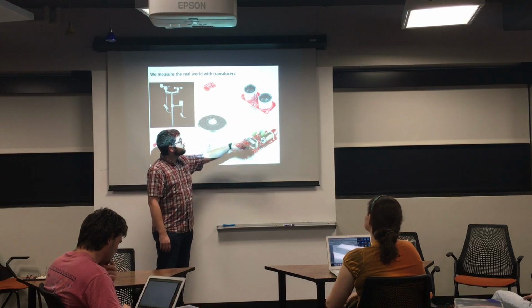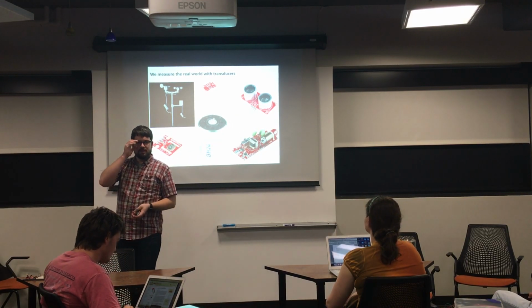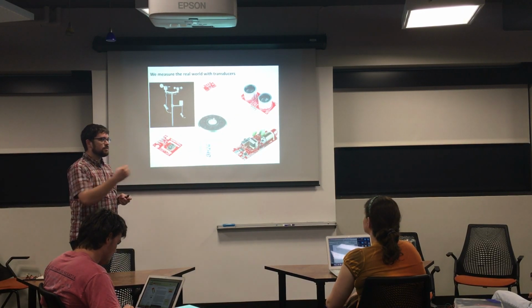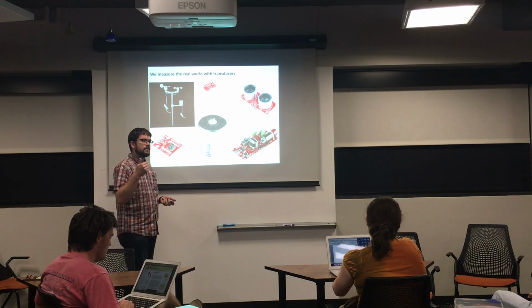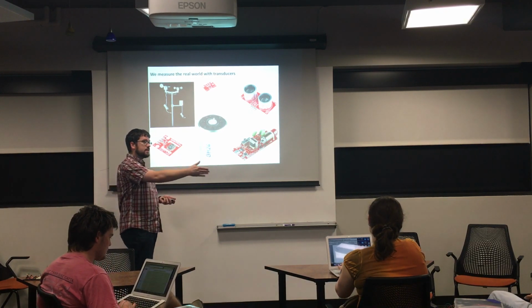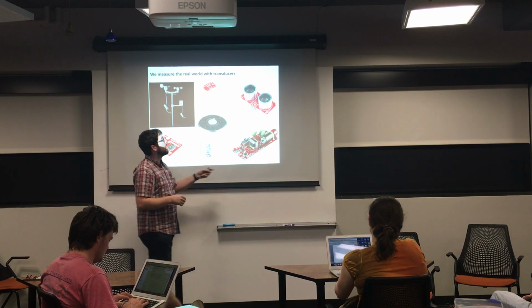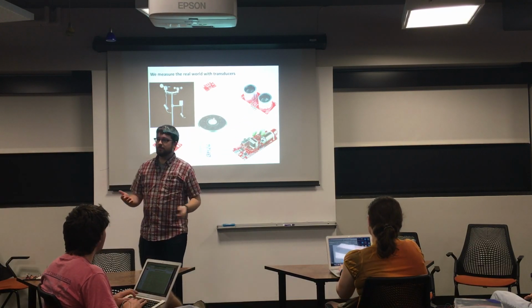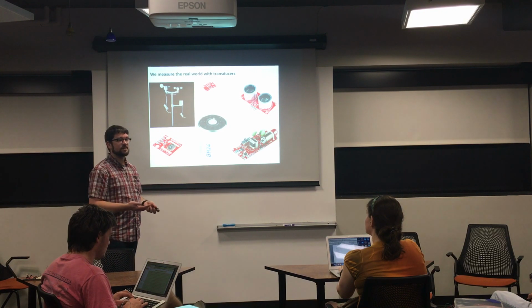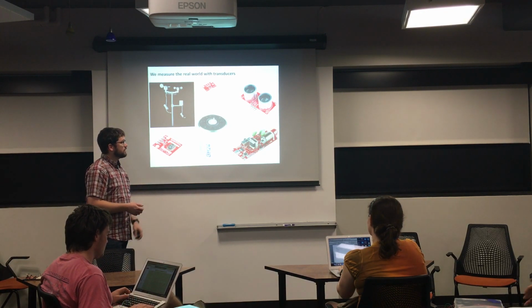And then the top right is an ultrasonic distance sensor. That actually transmits an ultrasonic pulse, a very short chirp of sound, above what we can hear. I think it's somewhere in the neighborhood of 40 kilohertz. It goes until it hits something, it bounces off, and this times that time of flight and tells you how far away it is. It's only accurate to about a centimeter, plus or minus, but for a lot of applications, that's good enough.